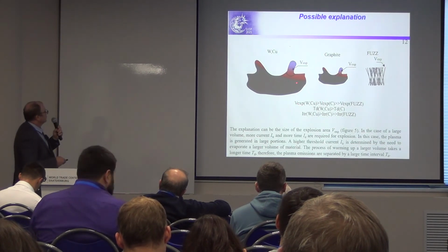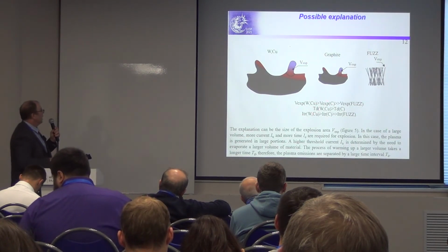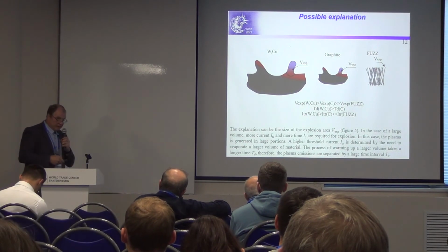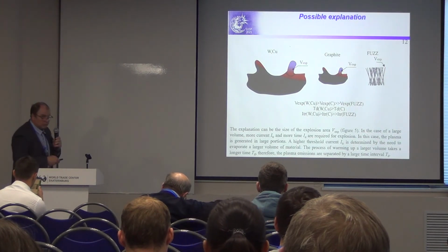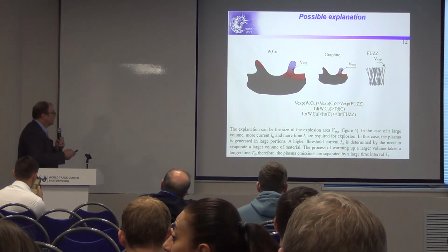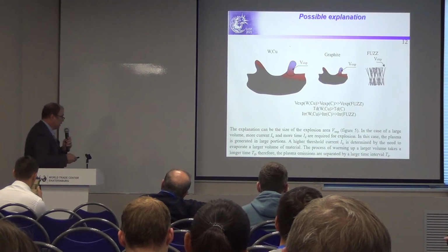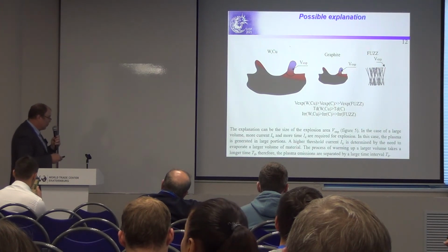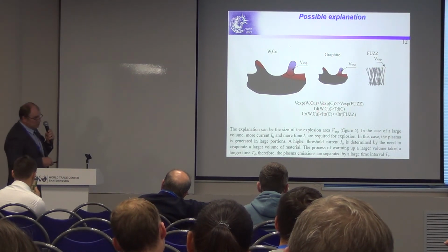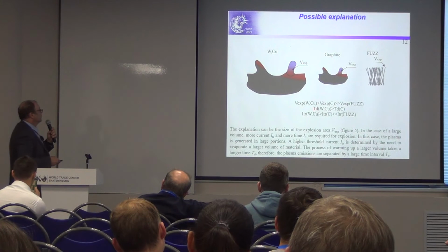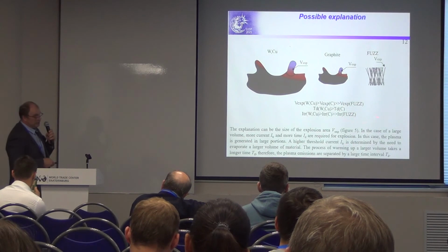The volume is big, and the time to evaporate is big, so the threshold current needed to evaporate and ionize this volume is too big. When the cathode material needs not much volume to evaporate, then the time of evaporation, the time of cathode spot life, and the threshold current could be much smaller.